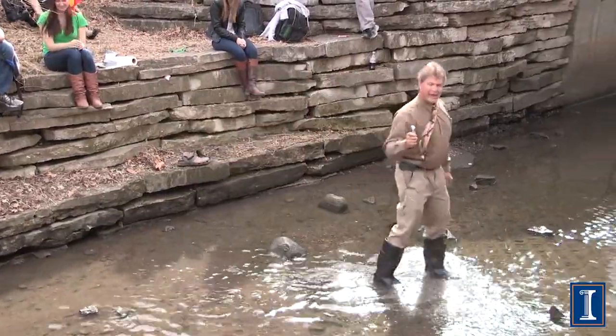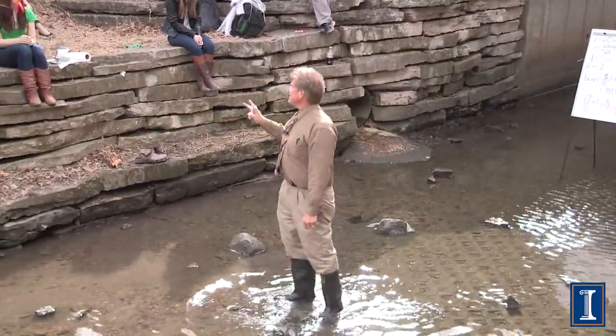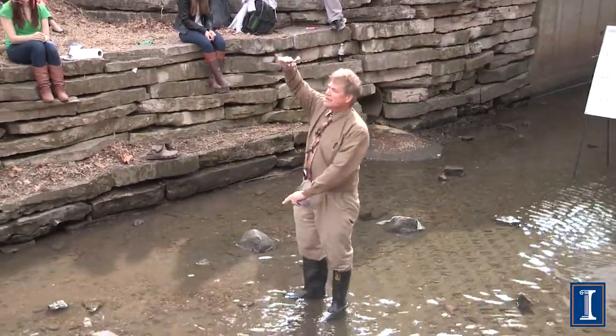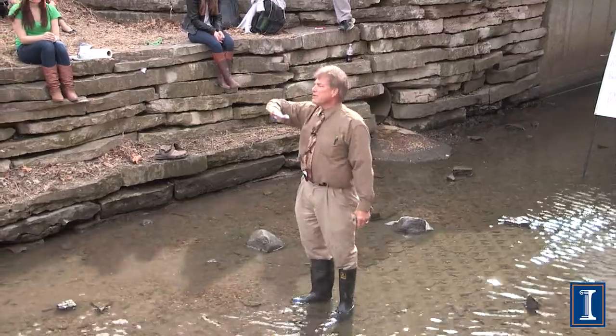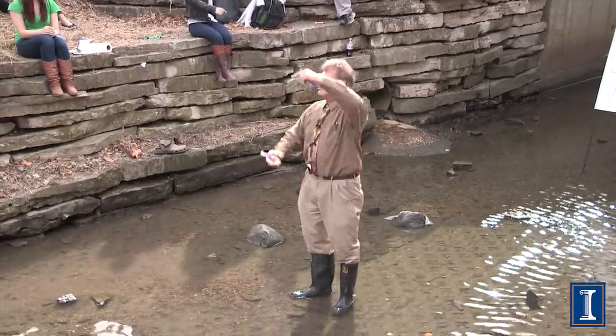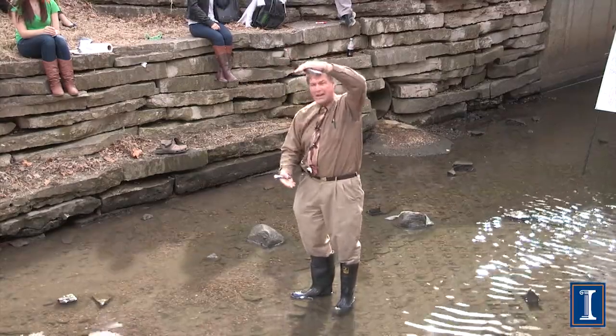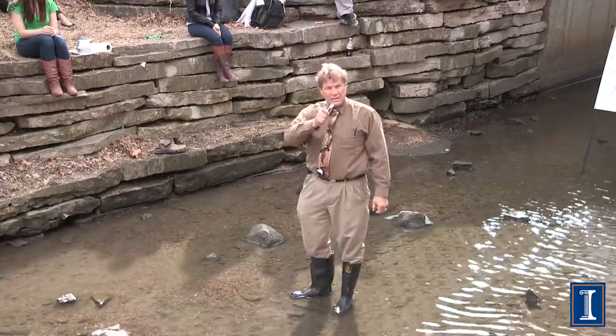For small-scale hydro, there are 2 minimum requirements. First, you need enough head. 2 meters, 6 feet. If you can't get 6 feet, forget it. It really isn't going to work. There's enough room for the turbine. You don't use something that small after all. It's got to have some height on it, right? So that's an important thing.